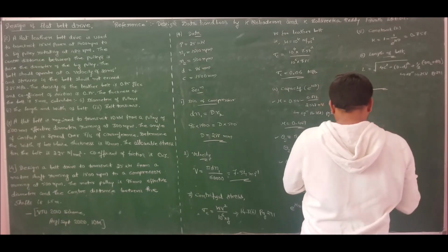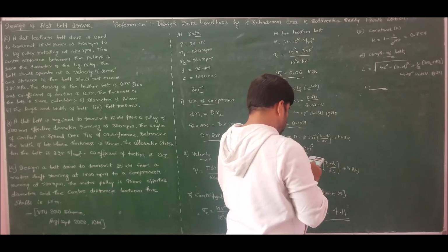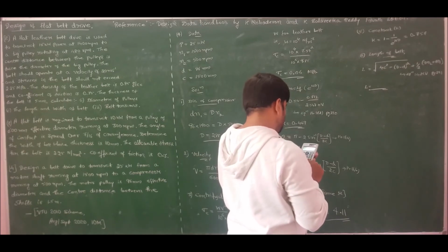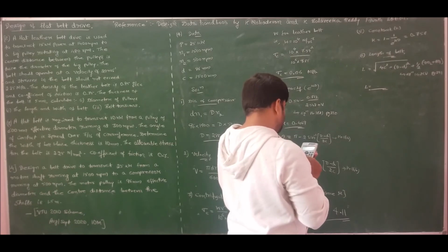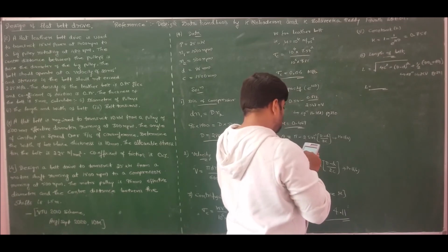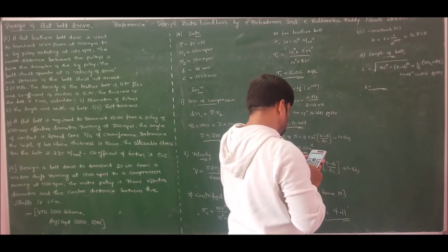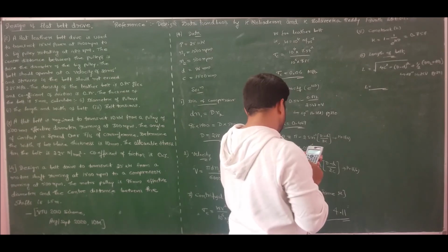So we know all the values. If I substitute and solve, I get the length as the root of 4 into 1500 squared minus (288 minus 96) whole squared, plus 0.5 times (capital D is 288 into theta L is 3.27, plus small d is 96 into theta s is 3.014).